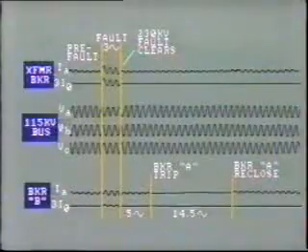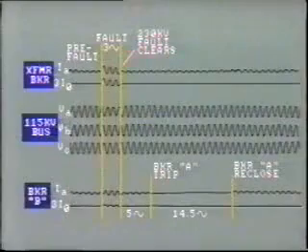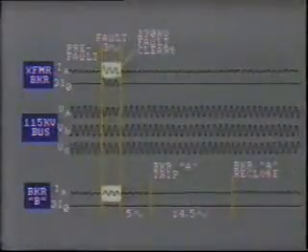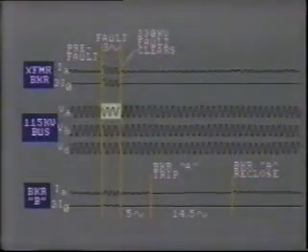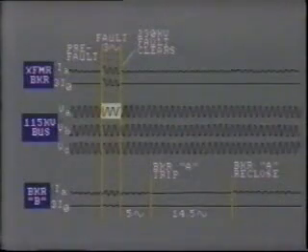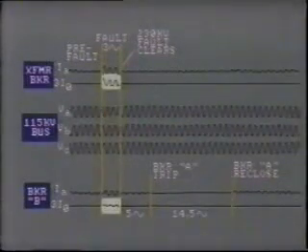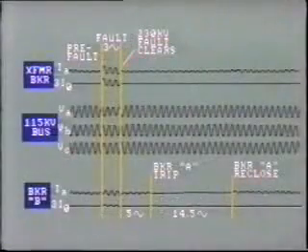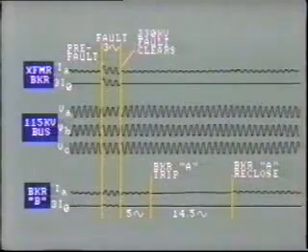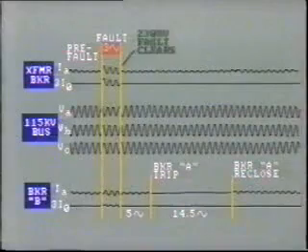You can see the onset of a single line-to-ground fault on the 230 kV line. The fault was on A-phase, as shown by the sharp increase in A-phase current through the transformer breaker and breaker B, and also by the depressed A-phase bus voltage. The presence of zero sequence in the breakers also indicates a ground fault. Tripping on the 230 kV system was correct, and the fault was cleared in just over 3 cycles.